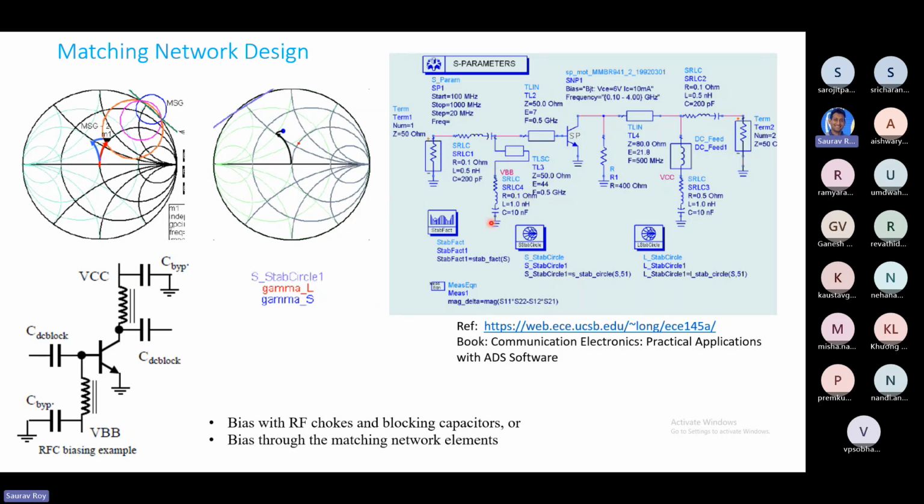So here they are all grounded because the large signal values are grounded. We are doing S parameter or small signal analysis. But ideally, in the actual circuit, you will have your bias connected to this point between this and here. VBB, VCC. Okay. VBB point here and VCC point here. That is why it has been.